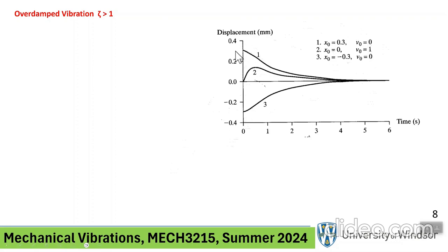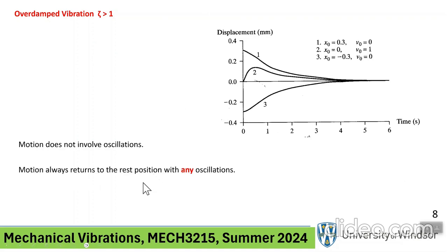In all cases, the solution is not oscillatory and it dies down. We can see that. As time goes on, x goes to 0. This is called an overdamped system. So there's no oscillation, and the object will always come to rest, but after an infinite length of time. Real life is not like that, but at least theoretically, it'll take forever for this thing to come to the equilibrium position, which is the 0 position.